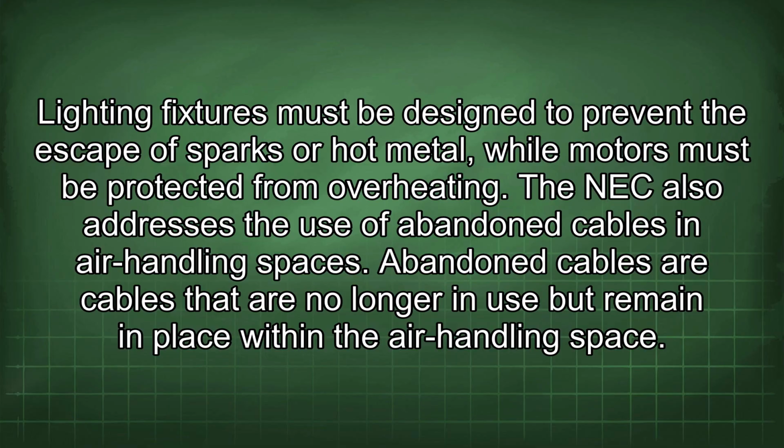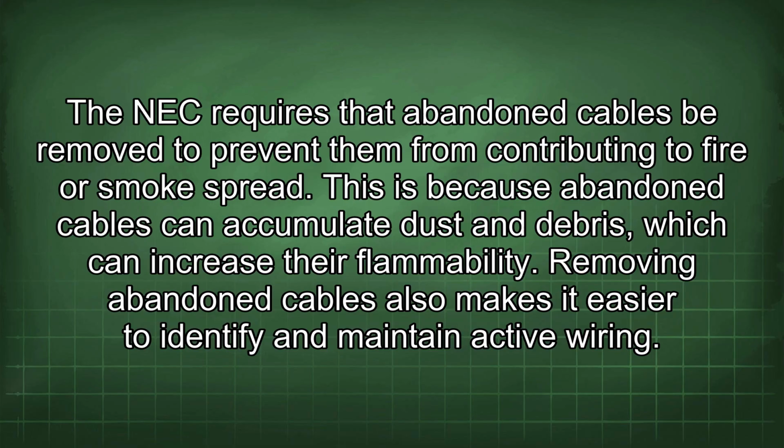The NEC also addresses the use of abandoned cables in air handling spaces. Abandoned cables are cables that are no longer in use but remain in place within the air handling space. The NEC requires that abandoned cables be removed to prevent them from contributing to fire or smoke spread. This is because abandoned cables can accumulate dust and debris, which can increase their flammability. Removing abandoned cables also makes it easier to identify and maintain active wiring.